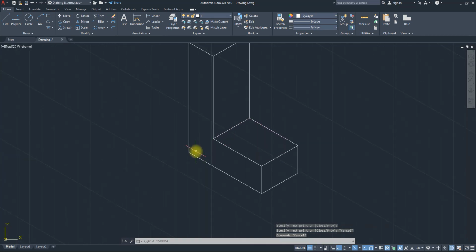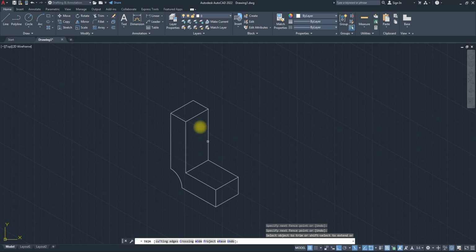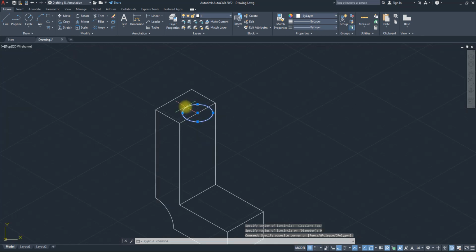Okay, so E for ellipse. So all the things we've done. I'll just use I for isocircle, pick this and go all the way here. So let's just say we're going 15. Then I'll trim this place, have that opening. And then E for ellipse, I for ISO, switch my view up here, move up all the way. So let's say we want to go 9 and select this.